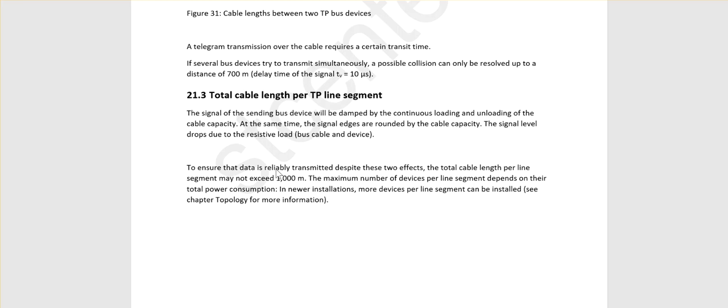If you can put 64 devices in one line, keep it between 40 and 50 devices, and use the line coupler or IP router and make another line.